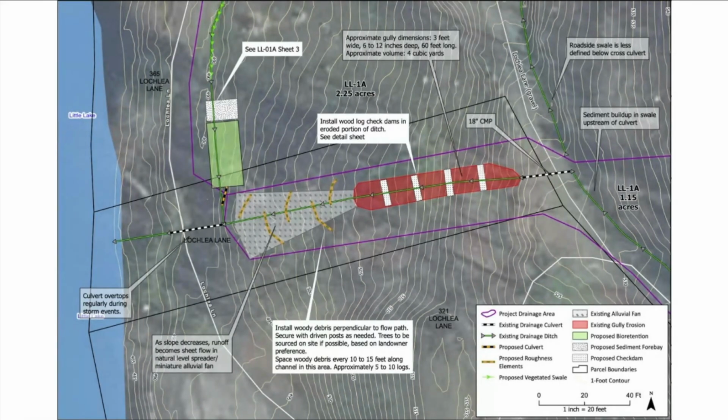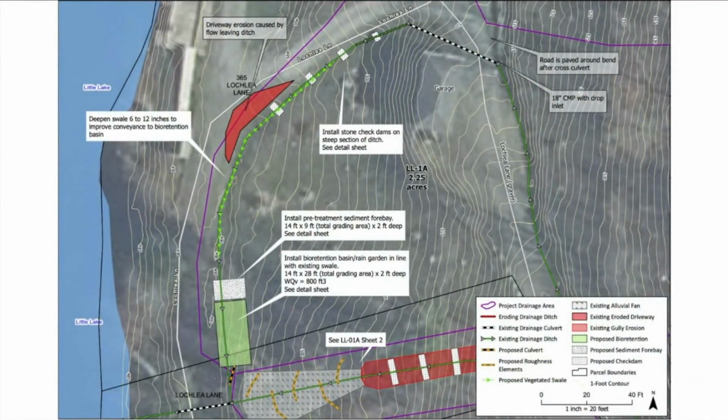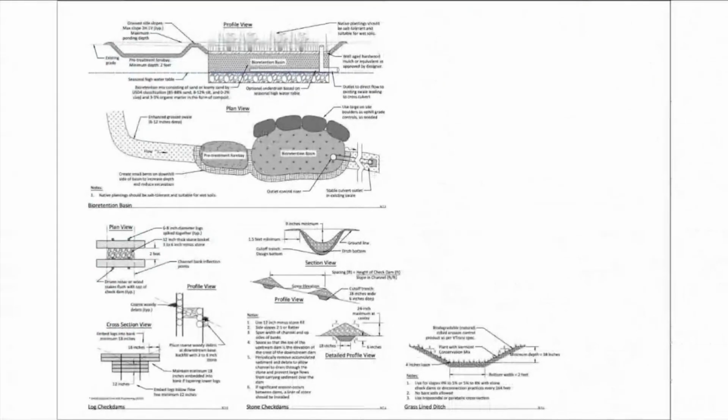Right next to it, to the north, flow comes around into that ditch you saw in the previous photo. And the green hatch is again a bioretention basin, taking about 2 acres. And here's a little closer look of it. And I think even a closer look in this nice illustration here coming around. We would put some stone into the slope to gain a little space and retain the slope in order to have a basin that could accommodate that flow.